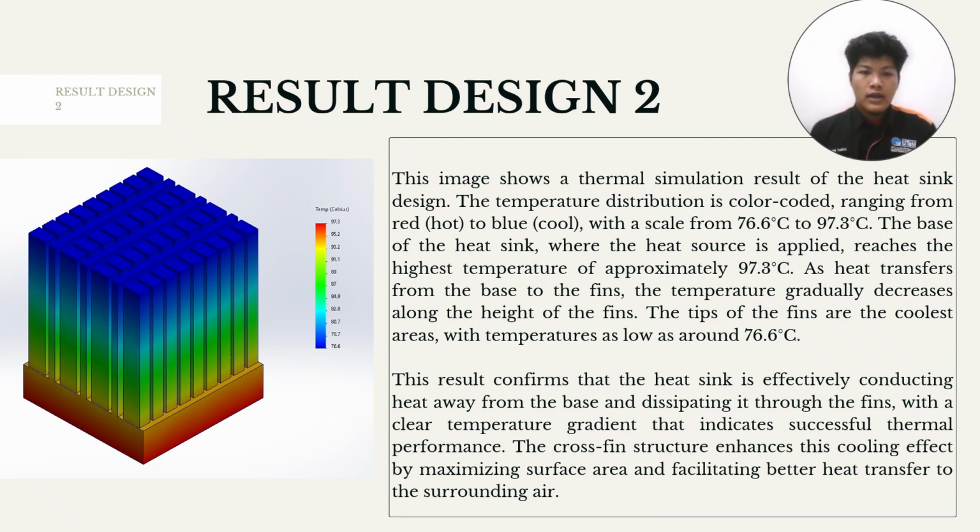The base of the heat sink, where the heat source is applied, reaches the highest temperature of approximately 97.3 degrees Celsius. As heat transfers from the base of the fin, the temperature gradually decreases along the height of the fin. The tips of the fins are the coolest area, with temperature as low as around 76.6 degrees Celsius.